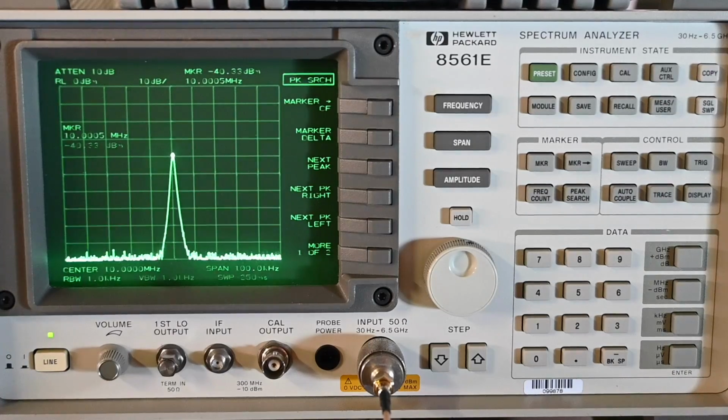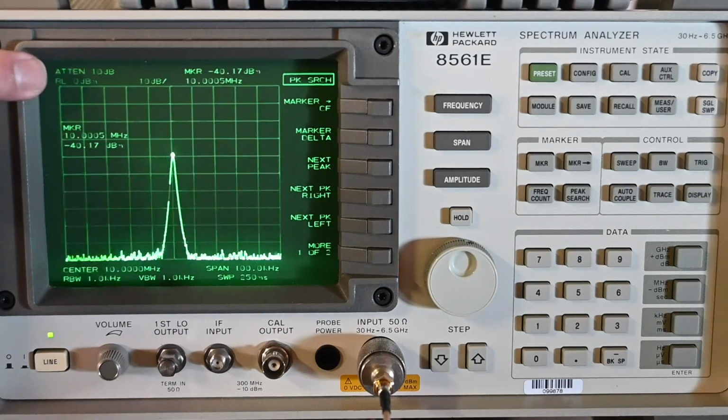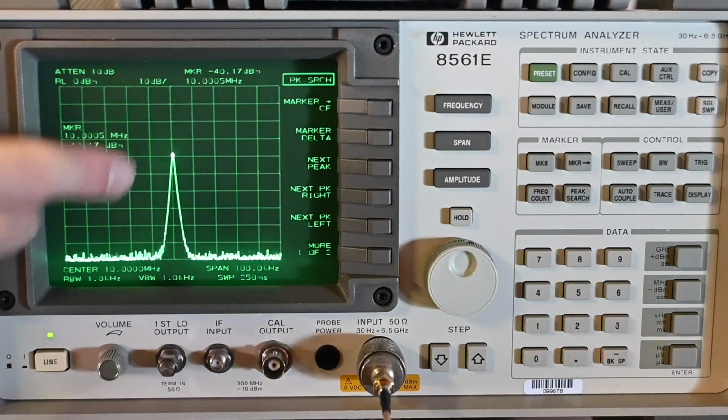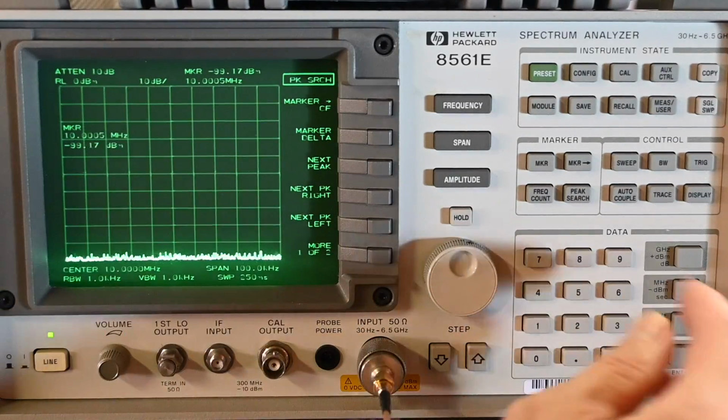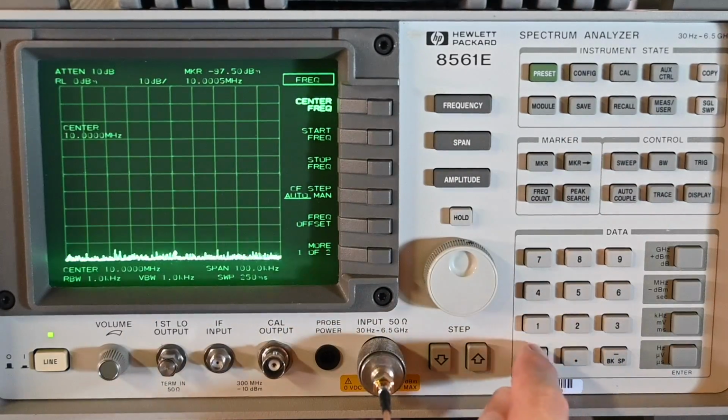Now, I just showed that it was in fact actually 0 dBm, and the reference line up here is 0 dBm. I mean, that is incredibly out of tolerance and out of spec. Definitely something wrong there. But take a look at this. I'll start increasing the frequency. So what I will do is just jump up here. Let's go to, say, 500 megahertz. And just do frequency 500.